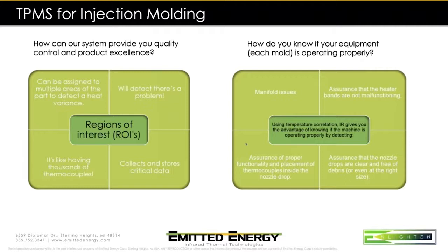So one of the areas we like to pick out and see how well your vents are going, so whether or not to be cleaned or need to be opened, or just by watching your vent areas, those are areas of interest to us on the tube, on the tool itself, as well as areas where your water flow will be, to make sure that we're getting proper Reynolds numbers in through there, and that you're consistent through all your water lines and things aren't starting to get clogged up, depending on what part of the country you grab your water from. They could be filled with a lot of minerals, and those areas can get pretty stopped up if the maintenance isn't keeping up with the acid etch on the tool.